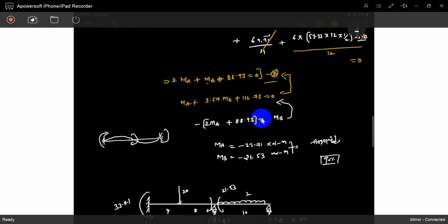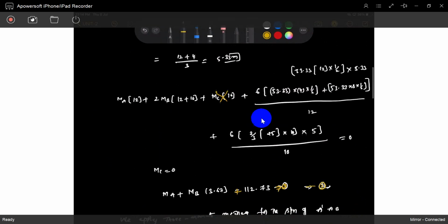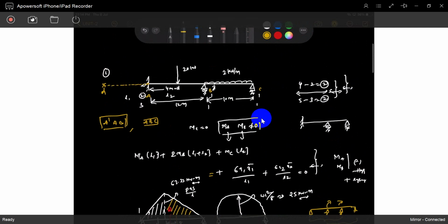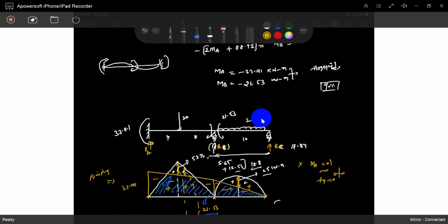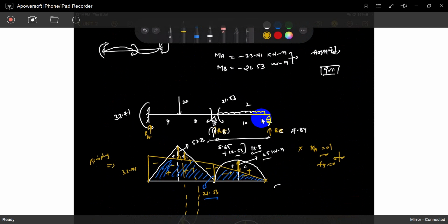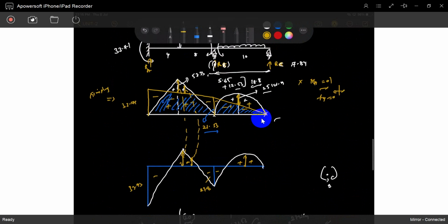And you can draw the deflection diagram also. What is the deflection diagram? I will draw it. Deflection is the deflection profile. See, it has points of curvature change. One, second, third, three points of contraflexure are there. The curvature changes at each point of contraflexure.